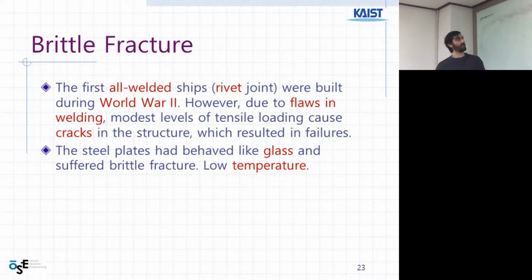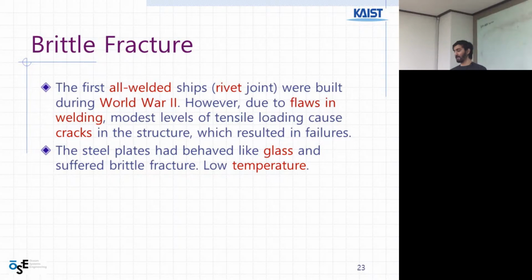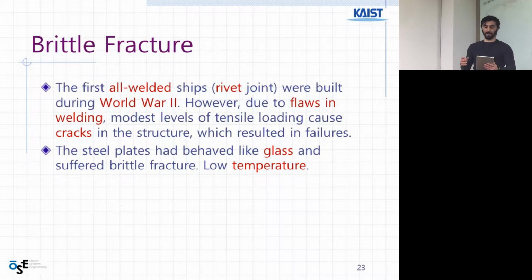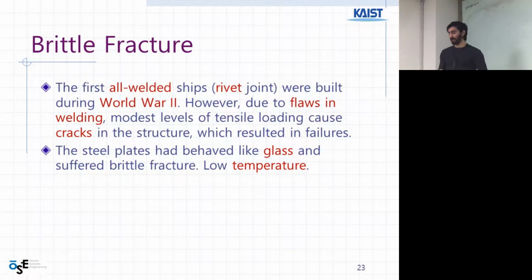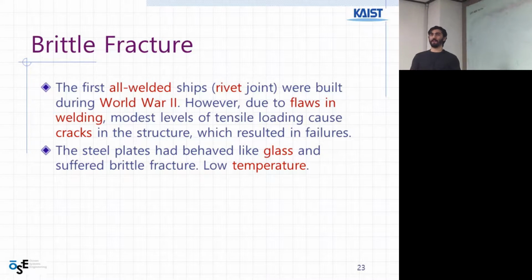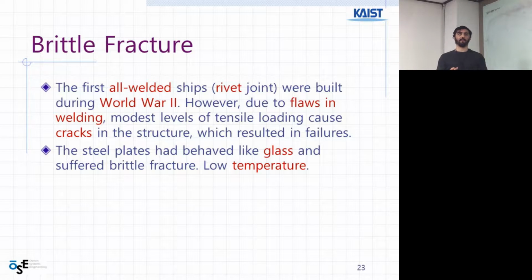So we start with brittle fracture. What is brittle fracture? It is the fracture of a material without appreciable prior plastic deformation. Brittle fractures that occur in surface are either initiated by the defects that were present during the manufacturing or the fabrication processes, or by the defects